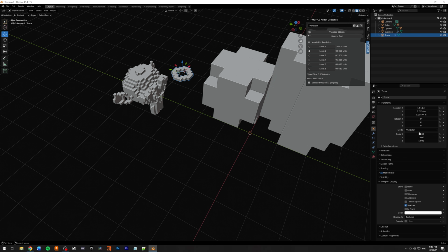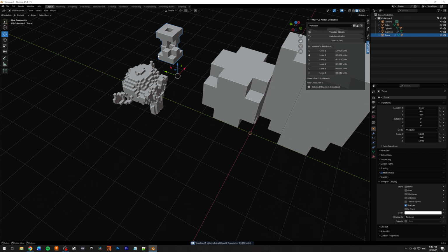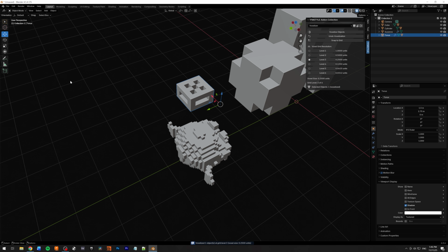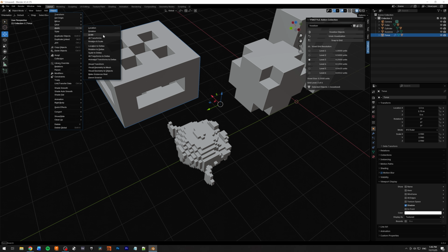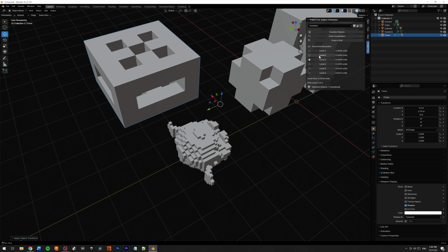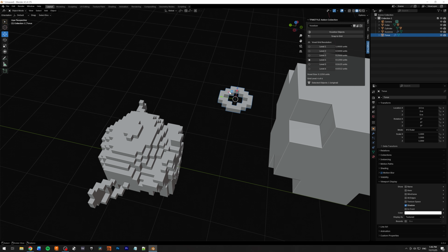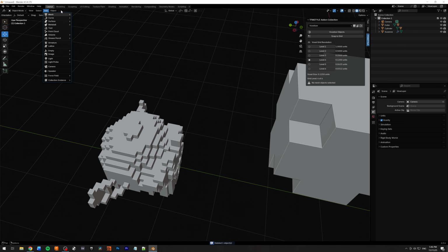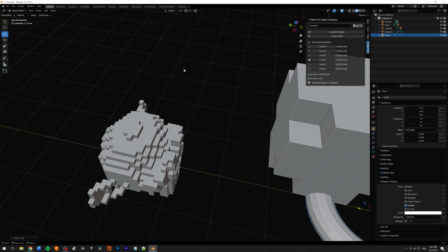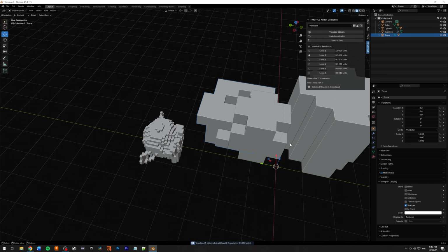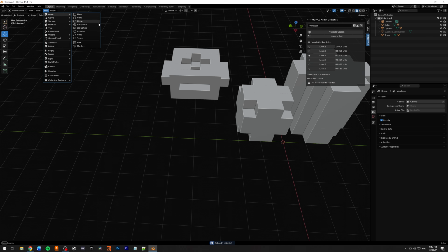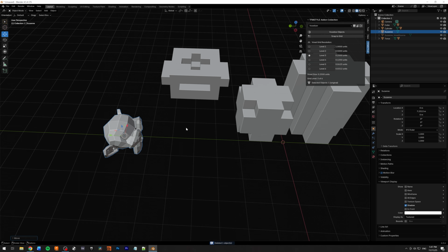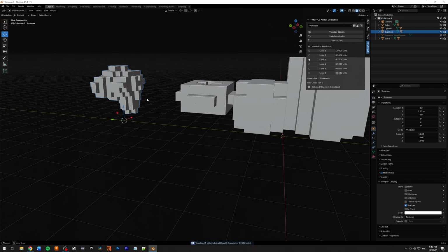I'm going to do the same. So the scale is 1, voxelize object. And if you need more resolution, you can simply scale this a little bit up, object, apply a scale, and now let's voxelize again at level 2. So for this one, we already voxelized it and I applied the scale. So I need to actually bring a new model and apply the voxelization on this new model. So I'm going to bring back a new monkey to be able to voxelize it properly.